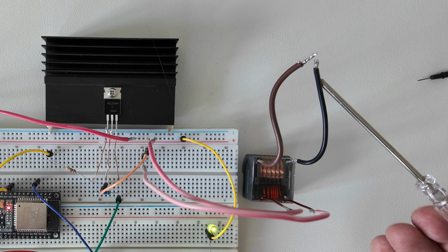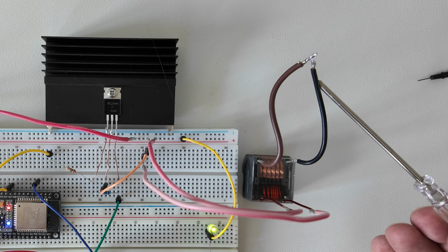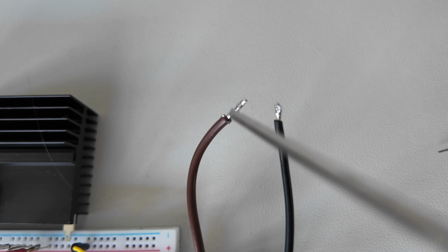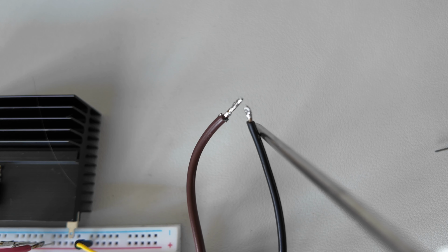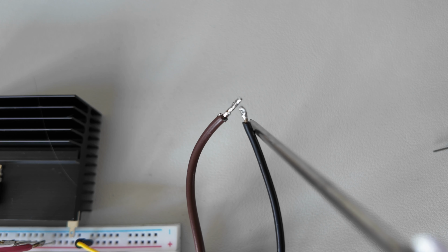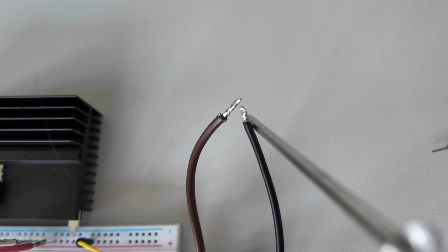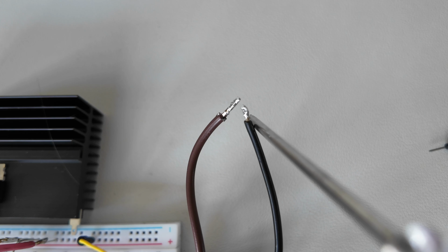And as a rule of thumb, 1 millimeter is equal to 1 kilovolt. So practically this gap is 1-2 millimeters, so we have something between 1-2 kilovolts. As we can see, it works. But I want to see bigger sparks, so let's connect the voltage multiplier.